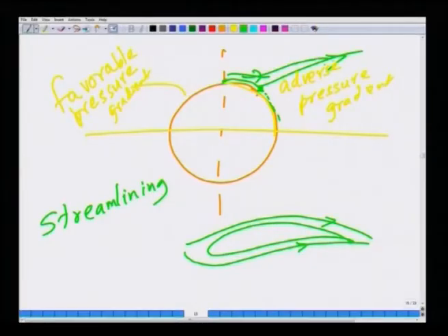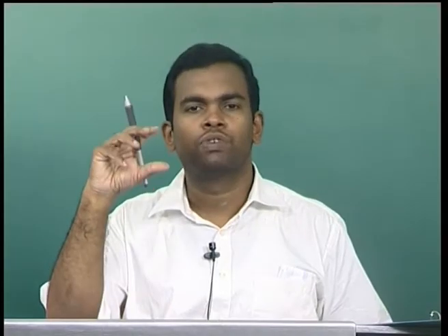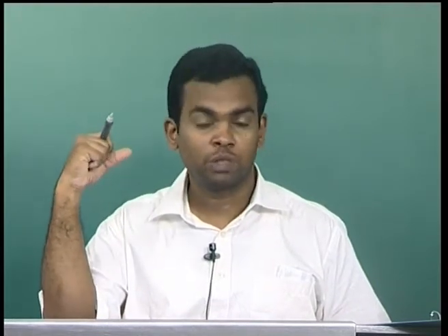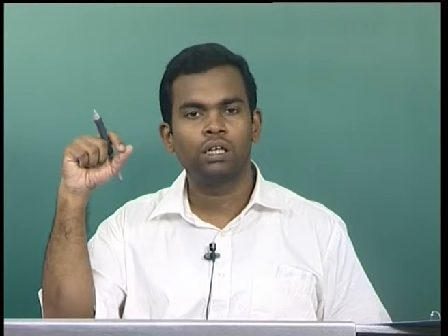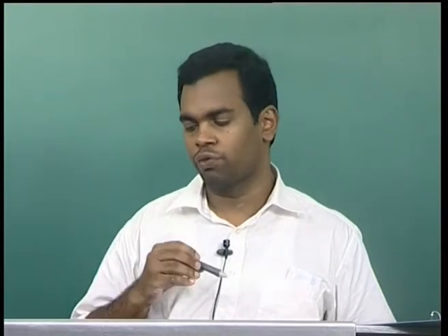When flow separation happens, the flow separates from the body, and there is a huge region where viscous effects become important, which is called the wake. So, our original proposition that viscous effects are not important in the bulk of the flow at higher Reynolds numbers becomes invalid. So, we should not consider problems wherein the flow separates.